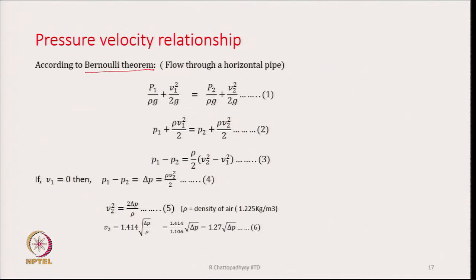We are writing this equation here, and the pipe is a duct which is horizontal, therefore elevation is the same, and hence the rho g h part which you generally see in the physics book is not there, because we are analyzing a situation where the duct is perfectly horizontal with respect to the floor.